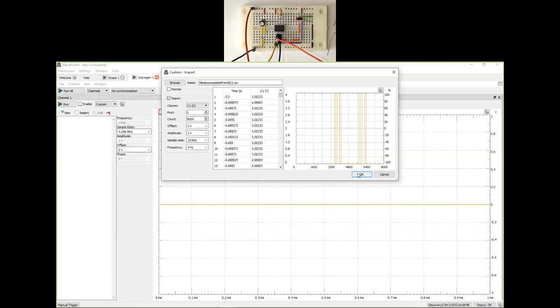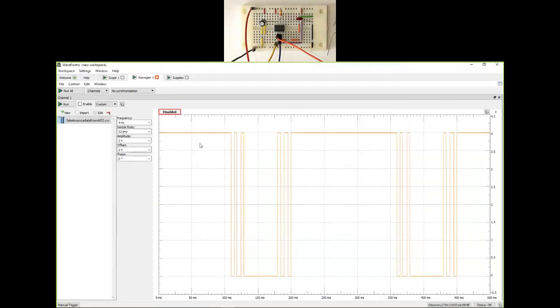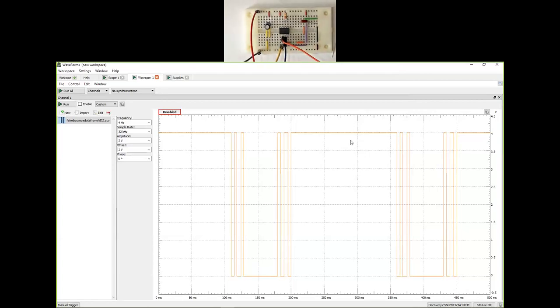So let's see. Once I say okay, I see that. You see, whatever goes into pin 2 remains high. When you press it, it goes low, glitches because of the bounciness, and then the normal or released state of the switch is when it is high. That is exactly the reason why I don't need a pull-up resistor in the fake data experiment. What we can do is perhaps make this a bit thicker so that you can take a look at the waveform that we are supplying to pin number 2 of the 555 timer.